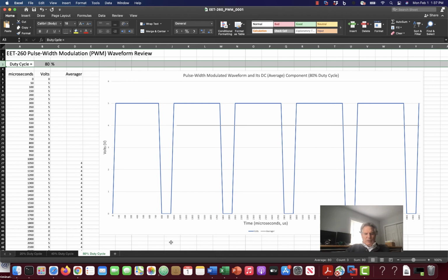So that's really what I wanted to say about pulse width modulation and duty cycle. Duty cycle is pretty easy. It's just the percentage of on time divided by the total time, the period of the repeating waveform. So I got 1 millisecond, and I'm on for about 0.8 milliseconds. I mean, that's an 80% duty cycle. So you can control your motor, and you'll see this happening in our other videos.